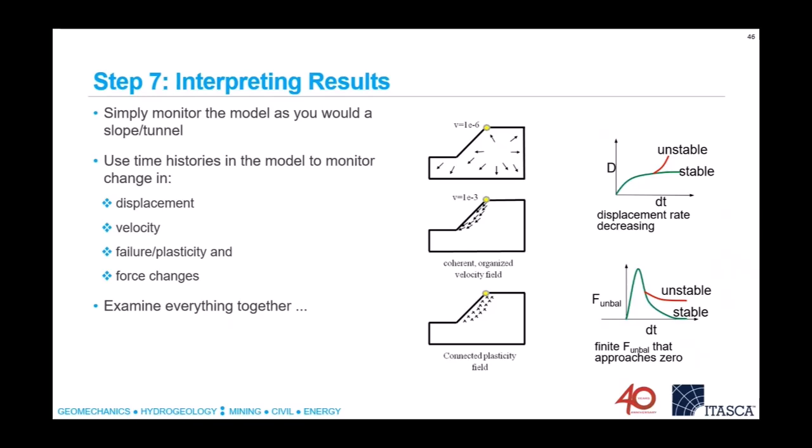By the way, these velocities don't have physical meaning, because remember, we modify the time step. It's not a real time step. So it's displacement per fictitious time step, or per one calculation cycle. Velocities don't have real physical meaning. They can only be thought about relative to something. Let's say this is our zero velocity field, and this is not zero velocity field, showing that things are flowing there, and maybe how fast they flow in comparison to something else.